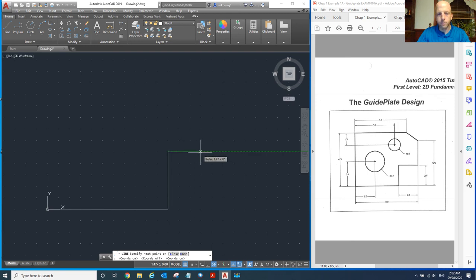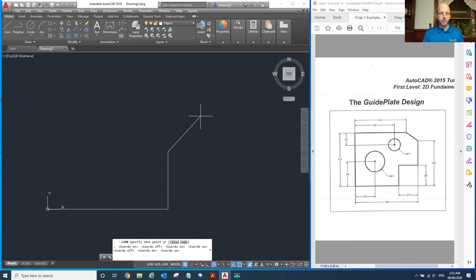So right there, that's a 1.47 inch long line at an angle of 0. Here we got about 1.43 at an angle of 37 degrees. So that's the polar way of specifying a coordinate. And this is just a coordinate display if I want to display it rectangular or polar. I can still type it however I'd like.